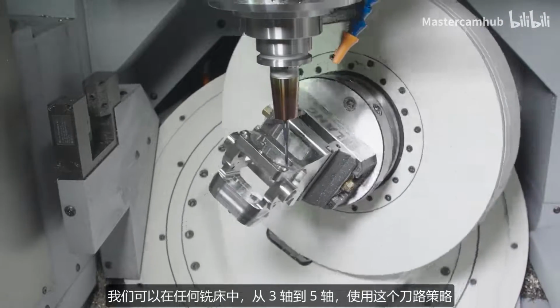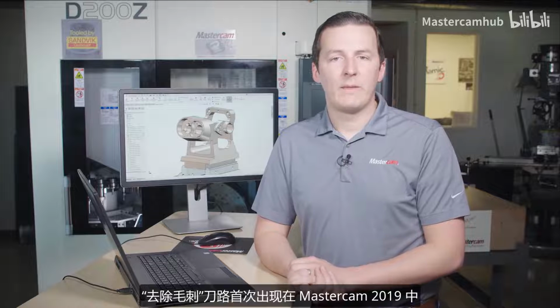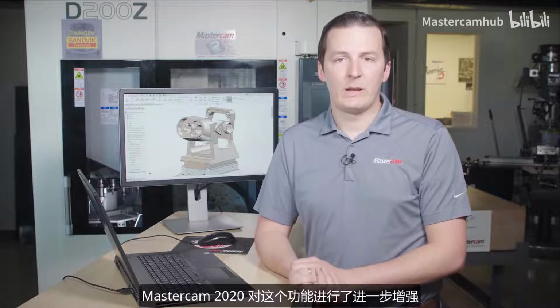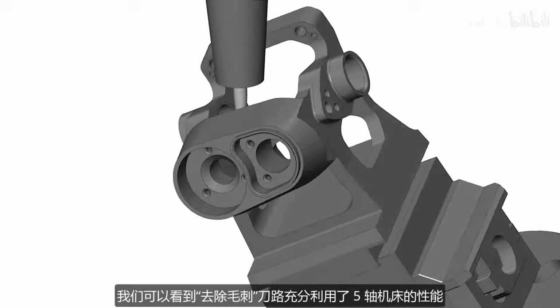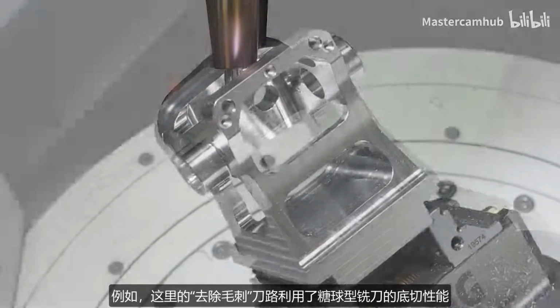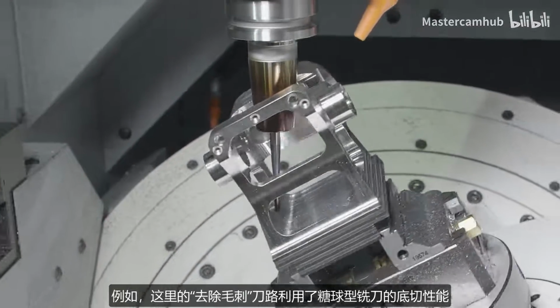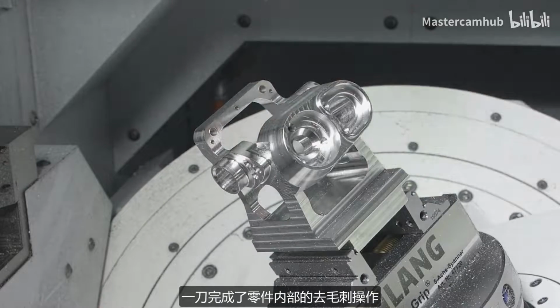We can use this toolpath in any milling machine from 3-axis to 5-axis. The multi-axis deburr toolpath introduced in Mastercam 2019 has received several enhancements for Mastercam 2020. This part showcases the full 5-axis capabilities of deburr with some spectacular results. For example, this deburr path handles the entire inside area of the part in one flowing pass, utilizing the undercutting ability of the lollipop mill.